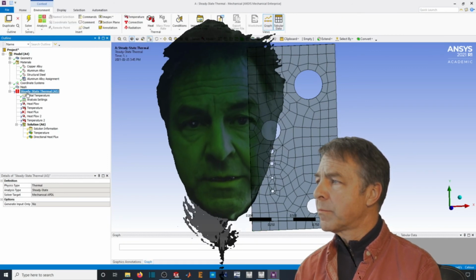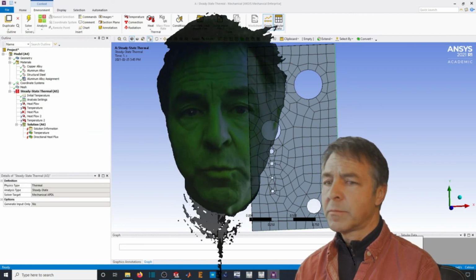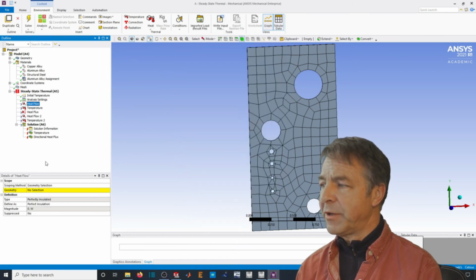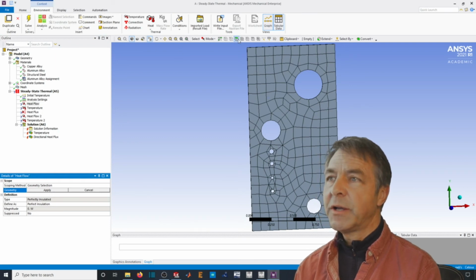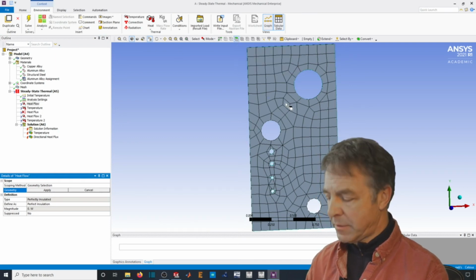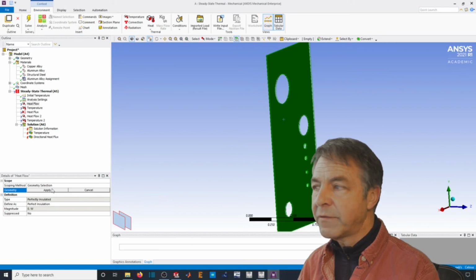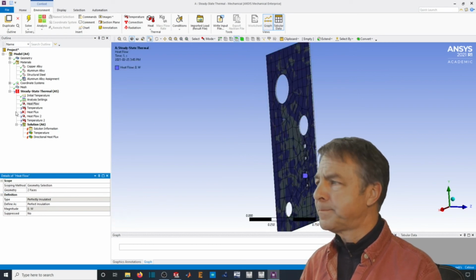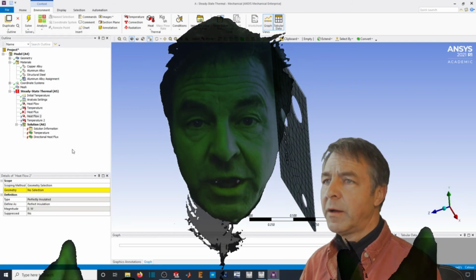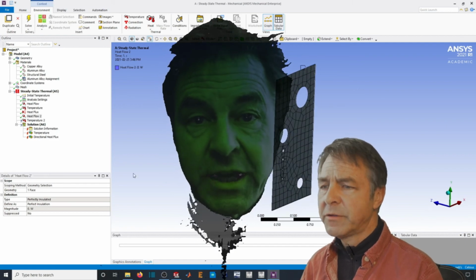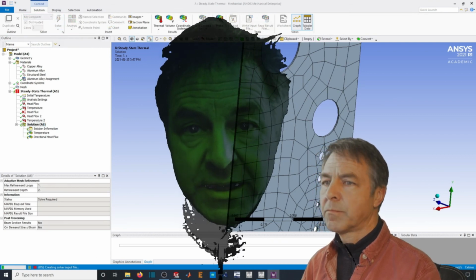And then you can cut a hole in it, like I showed in this last video. And that hole you can put in there, make it 10 centimeters at the center of the plate, remesh, and see what the result looks like. But they don't like our geometry. So we have to go back to the heat flow, which I selected on the basis of faces. And I selected that face and that face and apply. You're going to be looking for a temperature gradient, and you're going to be doing not a steady state thermal model, but transient. You haven't tried that yet.